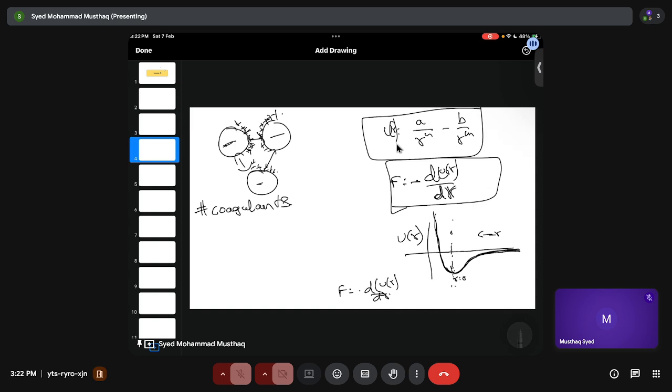Coagulants are mostly electrolytes which have opposite charge, and when we add them into the solution, they go and stick to the particle surface, neutralize the charge, and allow the particles to come in contact, which results in adherence, because of the molecular forces. This type of coagulation can be achieved by adding inorganic compounds, or you can even add organic coagulants which contain polymers.